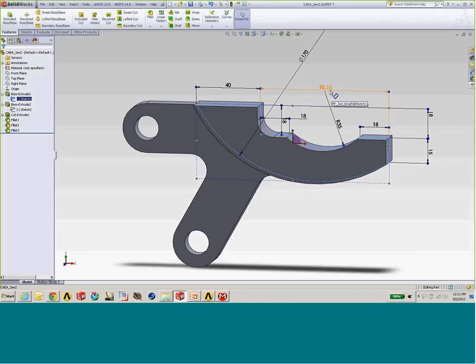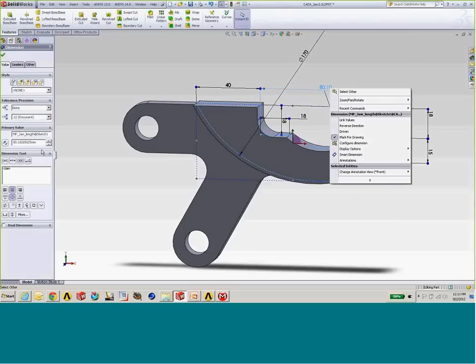Now, the way I identify particular parameters to be brought in with the geometry is to basically look at the details of that parameter and then assign to it a name that I'll be able to filter out when I sweep that geometry and pull out parameters. So in this case, I'm using a common parameter prefix of MP, so every parameter that I would like to bring into the analysis environment is going to have that prefix.